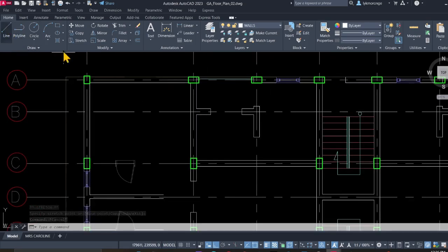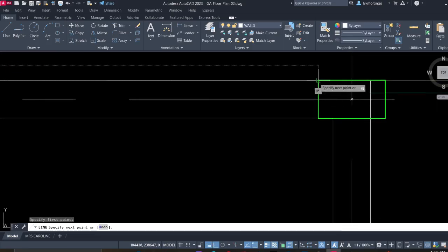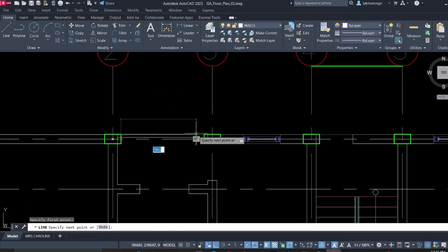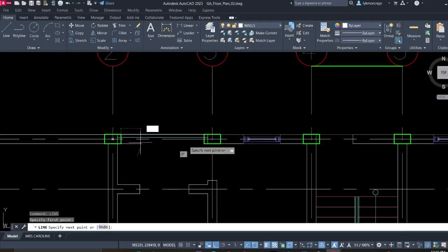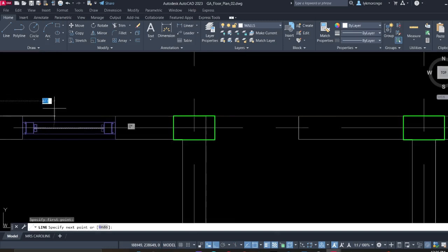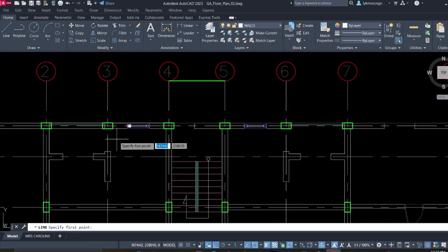You can actually even pick this, but remember that this one, you're just creating the beams to indicate where the walls will run, so that once you are in ProtaStructure you can actually see this. You will not need to do any type of referencing, you just work the model properly. So this is why we are just doing this.